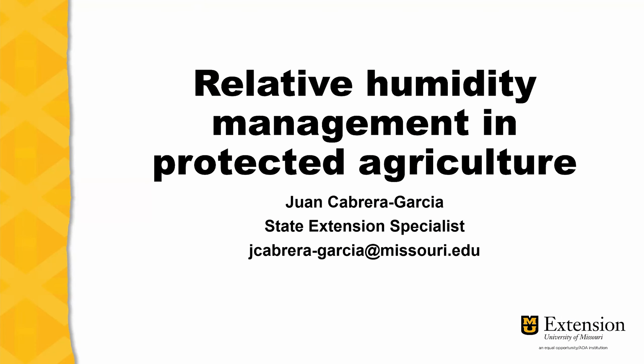Hello, my name is Juan Cabrera-Garcia, and I am the State Extension Specialist for Vegetable Production at the University of Missouri. So today we're going to talk about air quality management in a greenhouse, mostly focused on relative humidity because we see some issues with some vegetable crops when we grow inside a structure and we have high relative humidity.